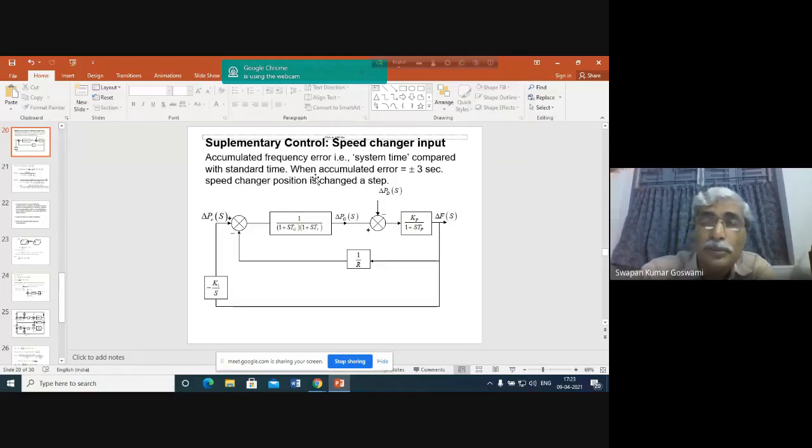To get rid of this situation, a tariff system has been devised by our electricity regulating authority. They have implemented a new type of tariff. This is called availability based tariff, that's why it's called ABT. It is connected to frequency. That means what should be the price of power, the price of energy, is connected with the frequency. How is it connected?